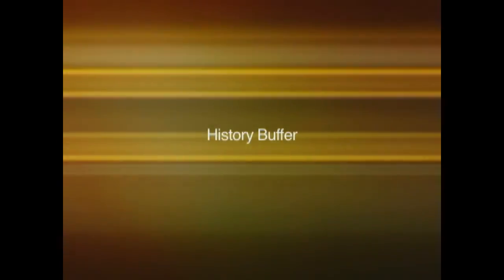On this alarm panel, there is a history buffer. The history buffer contains the last 650 events that have occurred on this panel. This is good for troubleshooting techniques to go back and find where all the previous alarms and trouble conditions have occurred.